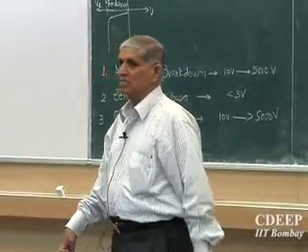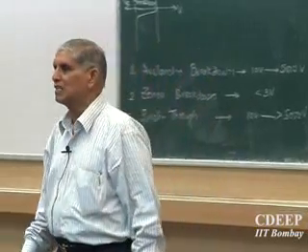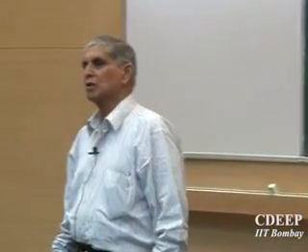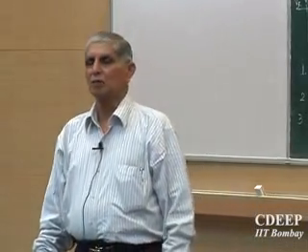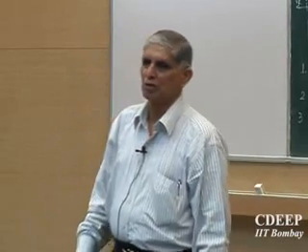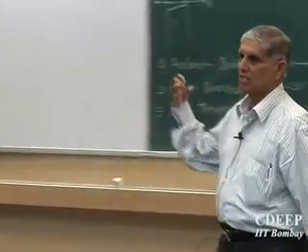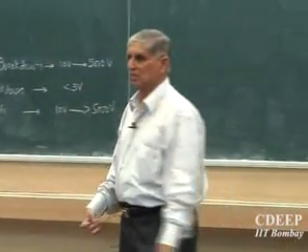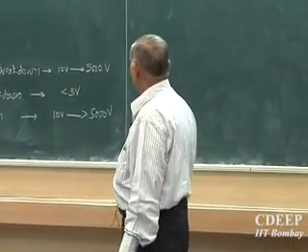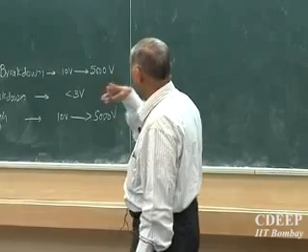In transistors for example, the base-collector junction at best can stand 30 volts. And therefore in most devices using PNP or NPN junctions, one finds that the breakdowns are typically low, whereas power devices can have breakdowns of the order of thousands. So let's look at the mechanism.